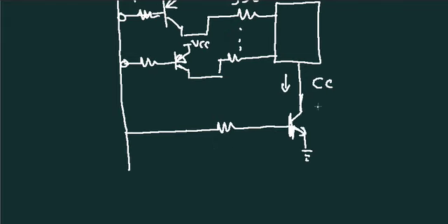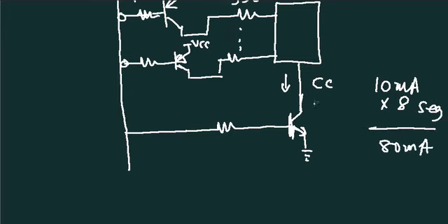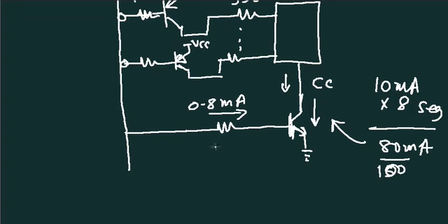This resistor should be such that it will be able to pass the required amount of collector current. So, typically if the segment current is 10 milliampere, maximum current for 8 segments, 7 segments plus decimal point, is 80 milliamperes. So, 80 milliamperes is the maximum current through this. If you consider the gain to be 50 or say 100, then 0.8 milliampere is the current required here. So, typically 1 milliampere. So, this can be near about 5 k. So, this can be 4.7 k.